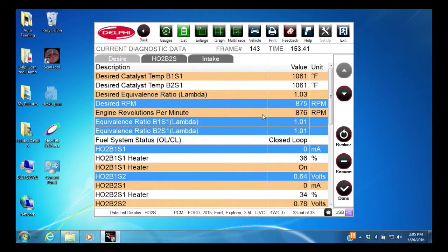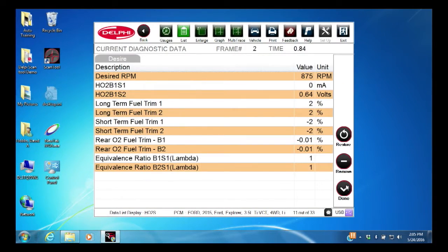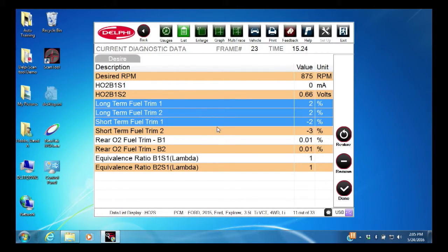So we'll go ahead and select that list right there and say done. So we'll make our PID list even smaller than this customized O2 section that we're looking at, of several hundred PIDs total on this late model Ford that we could see. Now that's drilling down to look at your air-fuel issues, and we are well in control. As I highlight long-term as well as short-term fuel trim numbers, they are all in low single digits.